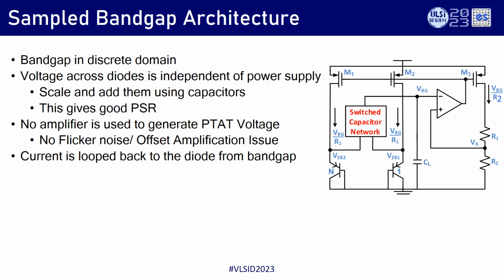Why? Because the op amp cannot distinguish the difference between the PTAT, because originally the op amp is there to amplify the PTAT so that it will cancel the CTAT and PTAT gain, PTAT temperature coefficient. But unfortunately, the op amp cannot distinguish between the PTAT or offset. So it will amplify the offset also. And so the final output is VBE plus alpha times PTAT plus alpha times